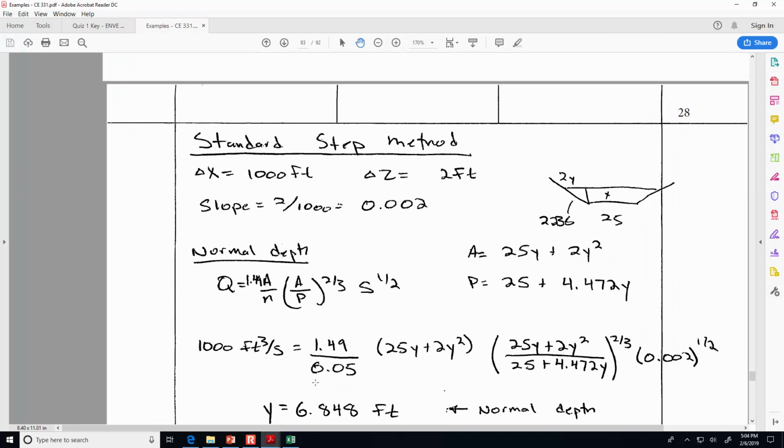So to calculate the Froude number, we substitute in the flow rate. So 1,000 CFS squared times the top width of 45 feet divided by g, 32.2, and 175 feet squared is the cross-sectional area at the conditions that we have. So if we substitute in when y is 5, that gives us a cross-sectional area of 175 feet squared, to the 1/2 power. So the Froude number in this instance is going to be 0.51. And anytime the Froude number is less than 1, that means it's subcritical flow.